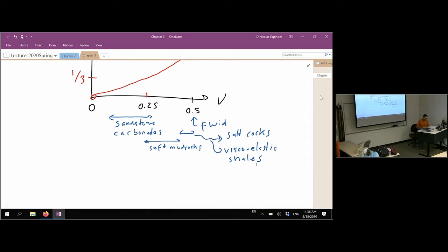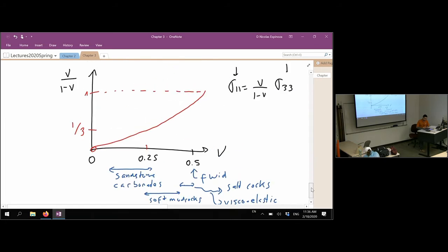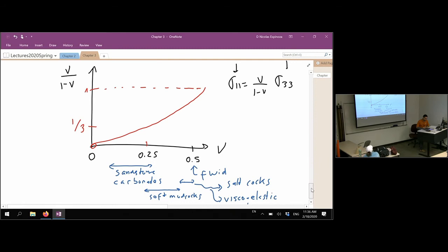And this is very important, because I hope that you see that this factor is going to tell you what the horizontal stress is, and it's going to affect directly, for example, what is the pressure that you need for hydraulic fracturing. In a rock in which the Poisson ratio is lower, your fracture gradient also will be lower because your horizontal stress is lower.